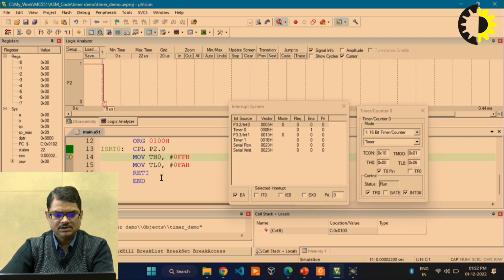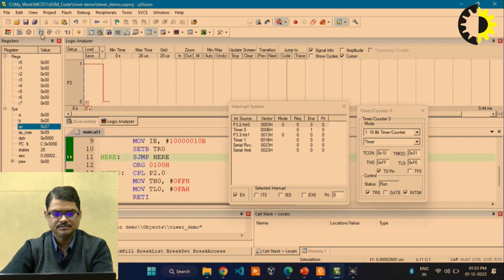You can see that even as we are executing this interrupt service routine written for the timer 0, with every instruction execution the value of TL0 is going to be incremented. Like this means that our timer is still on. You can see from here timer is still on and it is still counting. Now our bit has been changed. Now 1 to 0 transition has occurred, and here again we have loaded TH0 and next instruction TL0, and we are returning from interrupt.